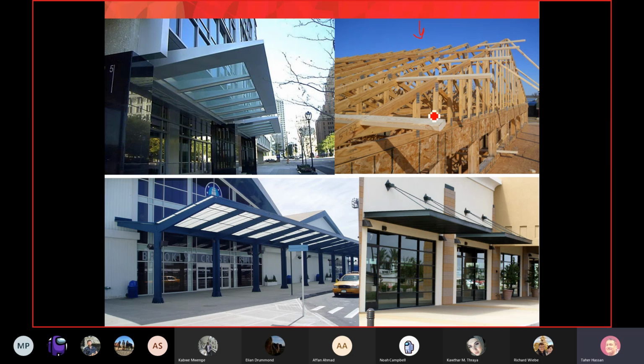We have those wood elements here. We extend them outside to support the eave overhang. And then we have a back span, and this back span is held back and anchored to the back truss. Okay. So in this case, there is no torsion because simply here is one member. So this one member here will be under bending moment. So under the gravity load of the eave overhang, simply this member will be under bending. Same thing here. Look at the bottom right picture.